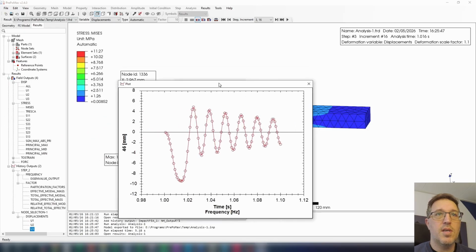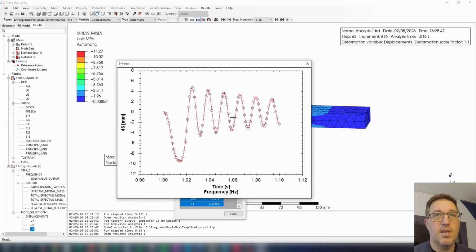This is how the displacement looks, including the damping. It's an impact, and we see that the results actually correlate with what we're looking for in terms of an impact, because it makes sense that when you hit something, it keeps vibrating to a certain level until it has decayed. And here we see, since we do have damping on the system, it just gradually goes down.